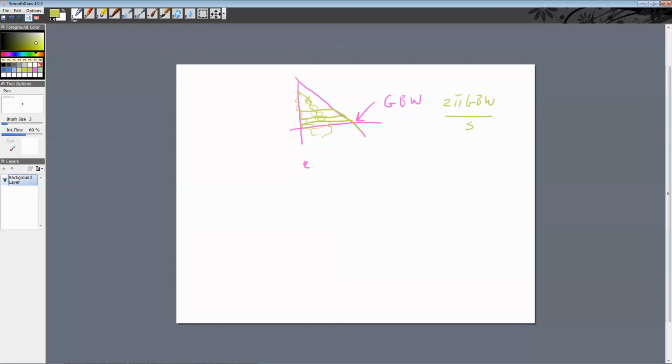The only difference is, if we don't have an ideal integrator, it does this, and this would be the open loop gain from the data sheet, and this would be omega naught. You can come up with that model. But really, the open loop gain at DC is so high that it's acting like DC, and it should still work.